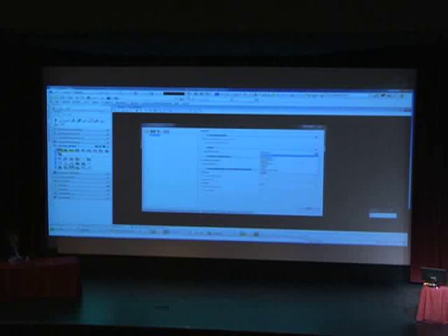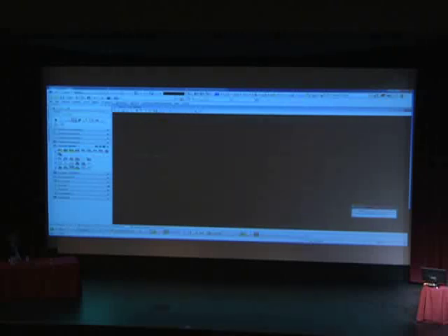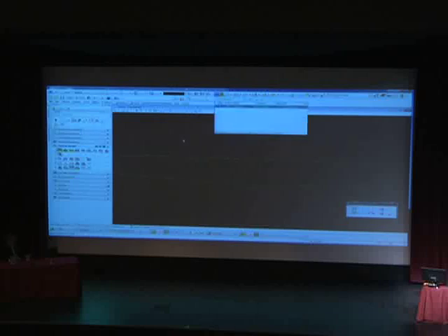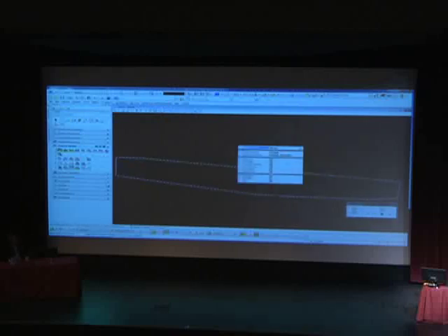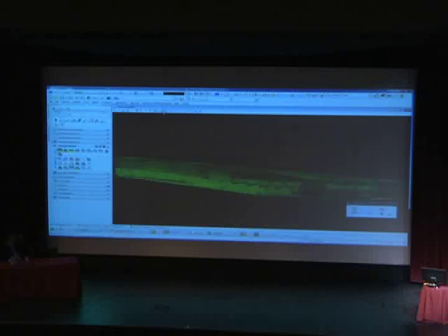All right, so I'm putting the units as US survey feet, and I'm selecting a feature definition of existing boundary. That's basically a level that you could use. All right, I zoomed extents just so you can see everything. I'm trying to rotate just to show you that it's in 3D. And then now I can turn on the triangles, and I can also turn on the contours.